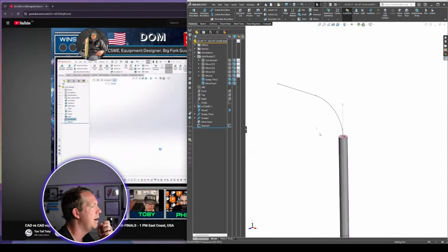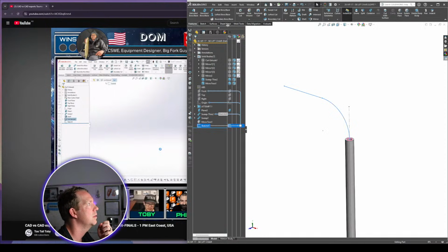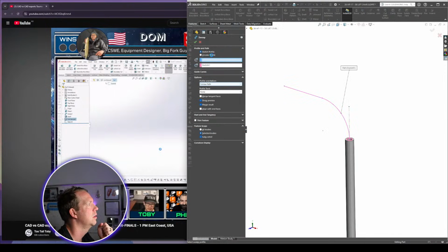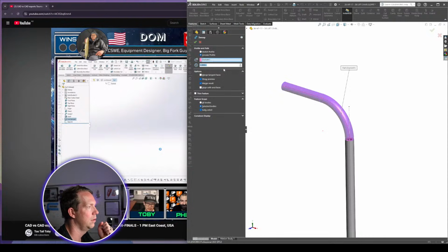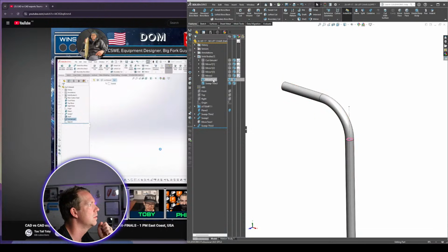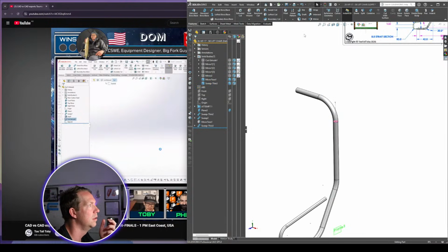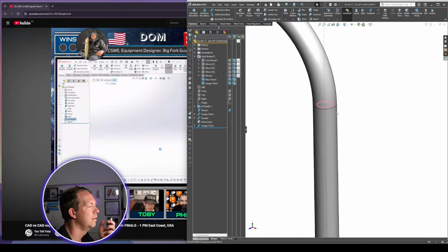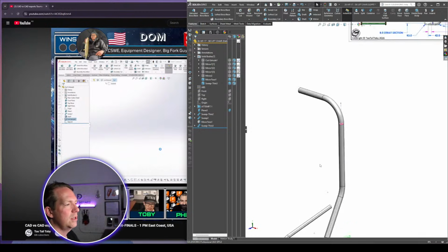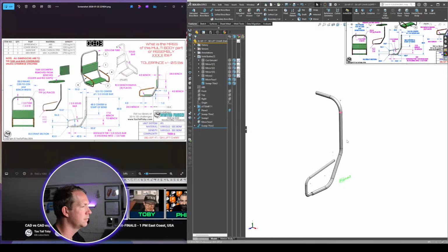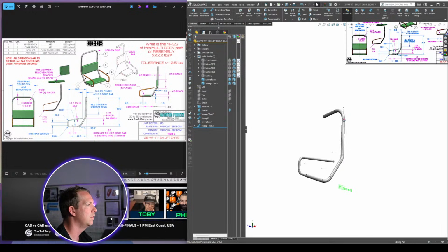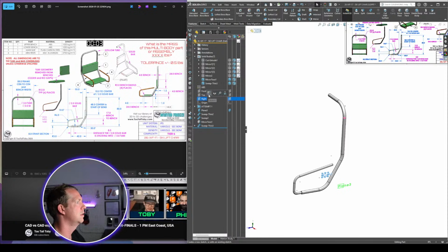We don't have to sketch because we can just do the same thing with this one. We can just do a sweep, circular profile, 3 with a thin feature, 0.5, just make sure it's inside and merging. As long as it merged, we're good. And now that looks okay. Some bug going on here visually in SolidWorks, that's all right. Okay, so that's the first 2 bodies, and then it's the seats.